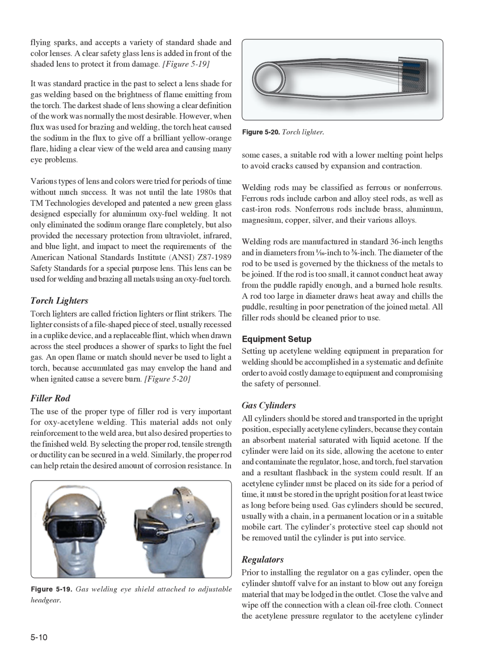Gas cylinders should be secured, usually with a chain, in a permanent location or in a suitable mobile cart. The cylinder's protective steel cap should not be removed until the cylinder is put into service. Regulators. Prior to installing the regulator on a gas cylinder, open the cylinder shutoff valve for an instant to blow out any foreign material that may be lodged in the outlet. Close the valve and wipe off the connection with a clean oil-free cloth.